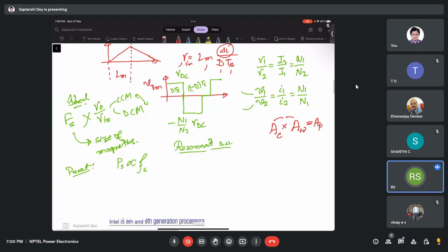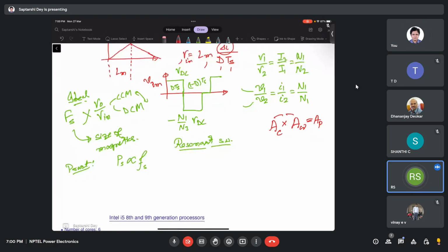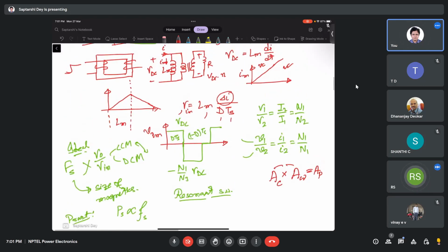Sir, while we are discussing the transformer now, the statement that the transformer works in transition state and not in steady state with DC, I have a little bit of doubt, because we have all the isolated converters working in steady state only with the DC. No, see, this is why I showed you this waveform. Look at this waveform here. If you look at the voltage of any magnetizing inductance of a transformer in any converter, at the end you will get bipolar voltage in all of them.